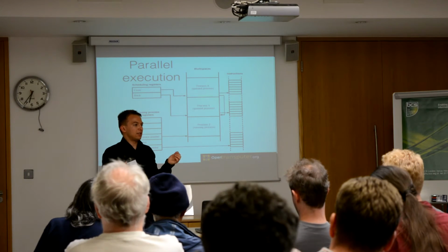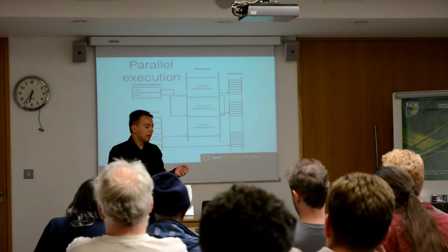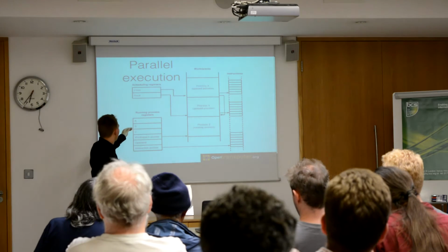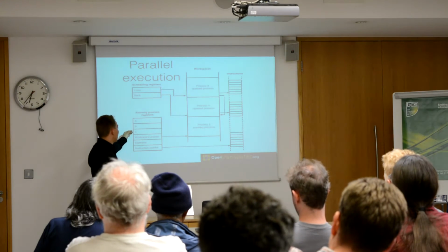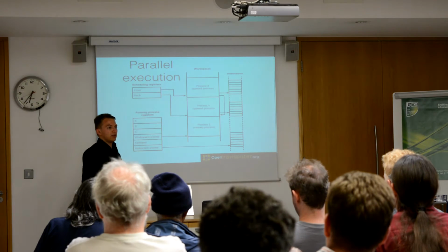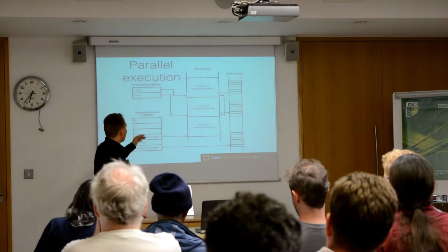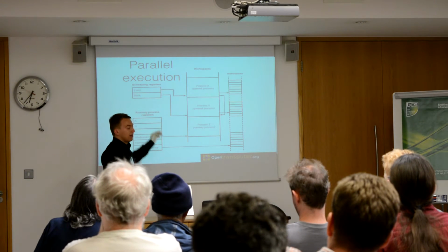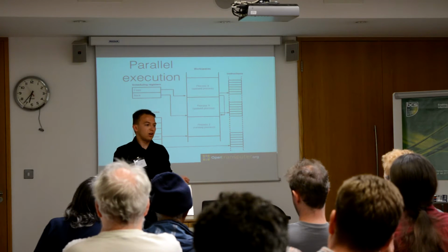A workspace is a location in memory where the context is stored, and the running process Z also has access to a set of registers. A, B, C, they form an evaluation stack, a workspace pointer, an operand, and an instruction pointer. The other processes that are queued are scheduled to be run, and this scheduler is implemented as a linked list in hardware.